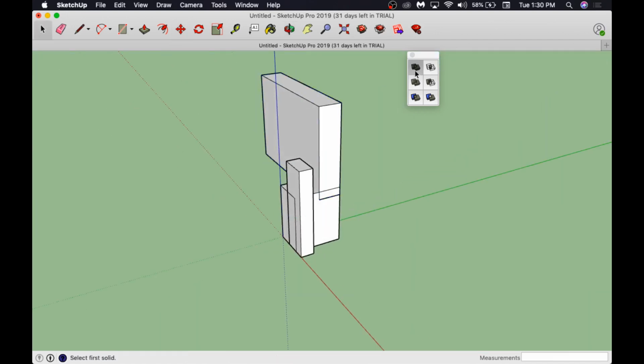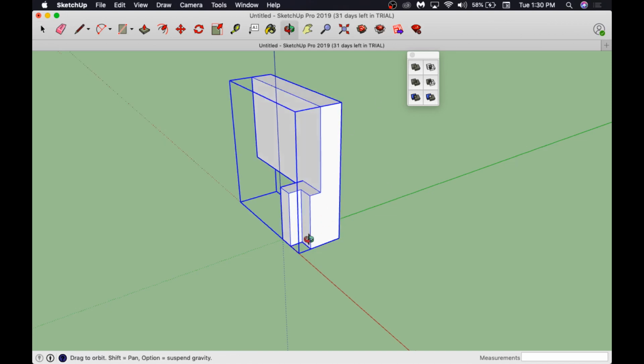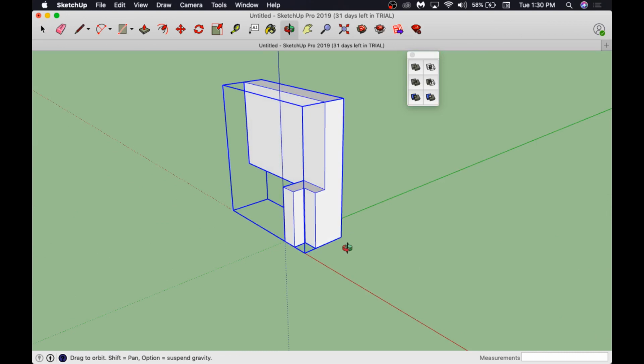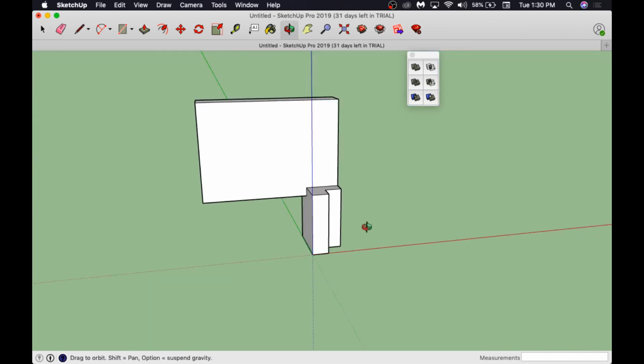We'll just go through these. Select one and the other, especially if you're uniting them together. It's just looking for groups, and it makes it one continuous group. And then we can select one and the other, and we can tell it to subtract, and so subtract that object from there. So that's the basic solid tools. You can just set that up however you want to move things.